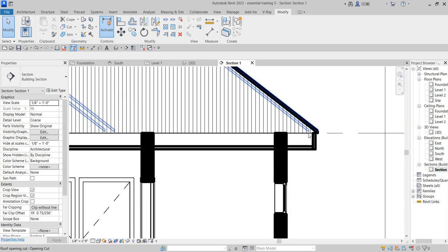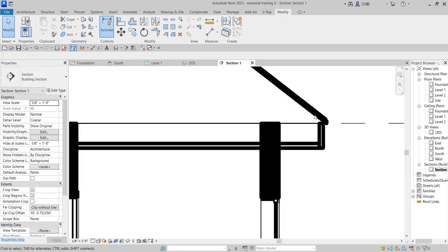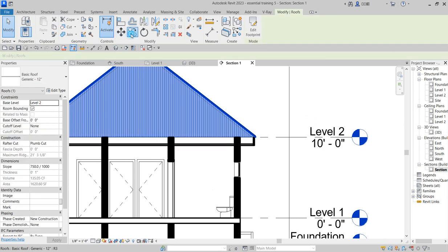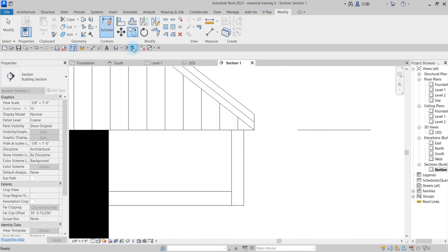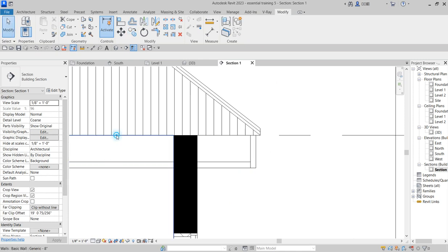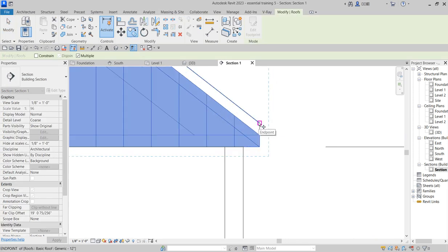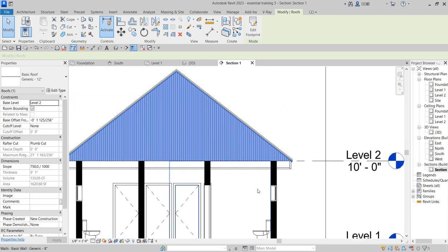So you copy this roof. See what I'm saying now? You copy the roof to another layer of roof. So reduce the thick line of this. Press escape, select the roof again, and you say copy from the top of this to somewhere below. So this one now, you change the trusses.